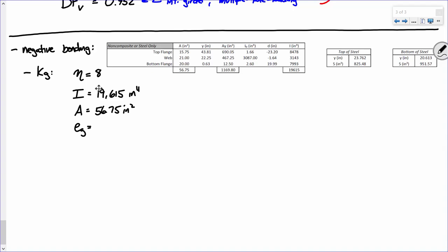Web depth, haunch, half the slab thickness, and then we subtract the centroid, right? So help me out with the dimensions. Make sure y'all paying attention. What's the bottom flange thickness in that negative bending region? Remember, right there around the pier, that middle support on that beam. 1.25 inches.